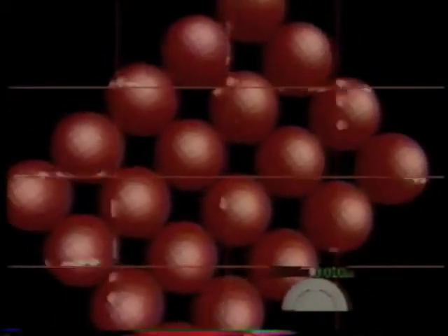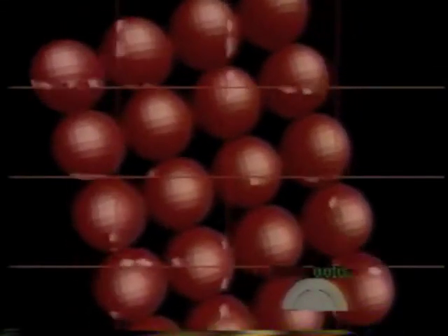The gauges in the lower right tell us the following information. The green number is the number of primitives transformed. The red number is the number of primitives rendered to the screen. The green inner gauge shows the number of highlighted primitives as a percentage of the transformed primitives. The red outer gauge shows the number of highlighted primitives as a percentage of the rendered primitives.